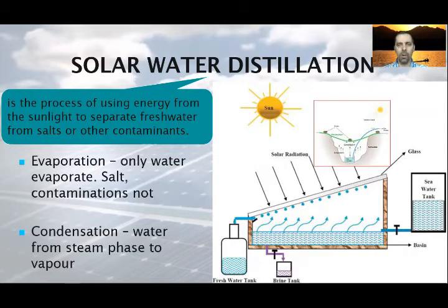Sunlight that is absorbed by the black material speeds the rate of evaporation. The vapor is then trapped by the clear topping and funneled away. Solar stills can be used for low-capacity and self-reliant water supplying systems, because most stills need to be about 6 square meters in size to produce enough water for a single person for a day. Multiple solar distillation systems are required to produce a large quantity of distilled water.